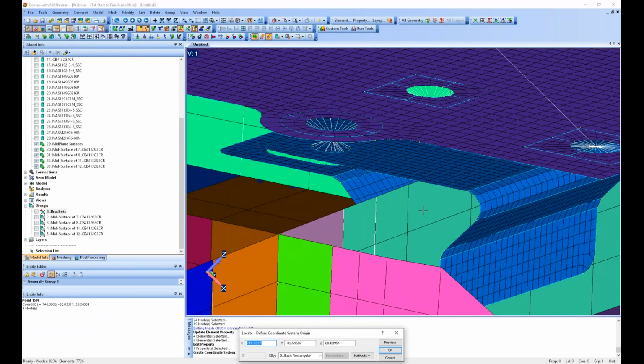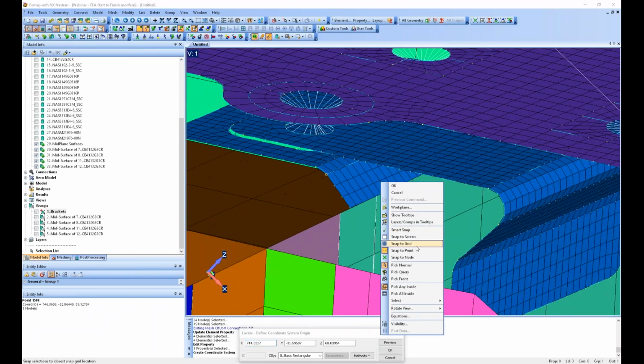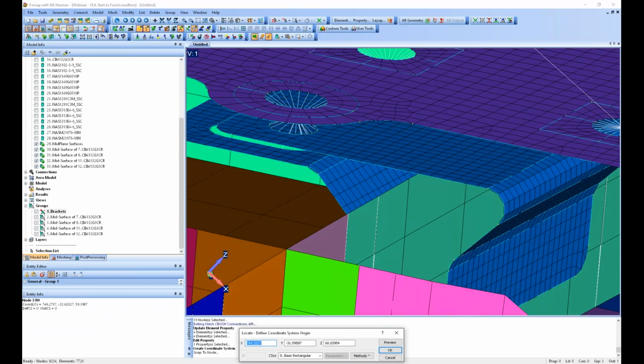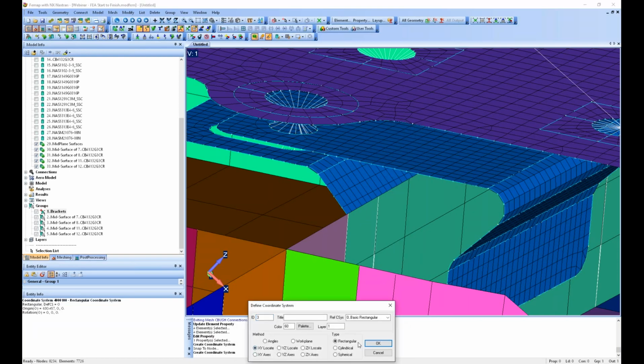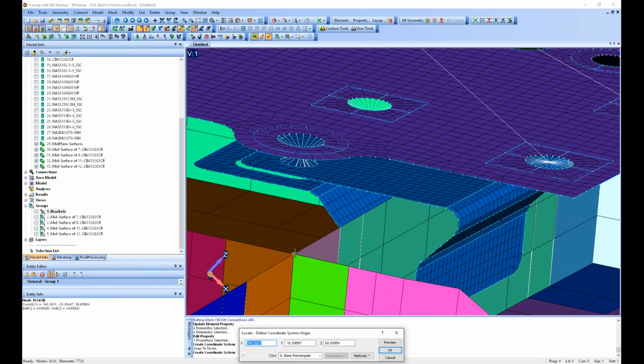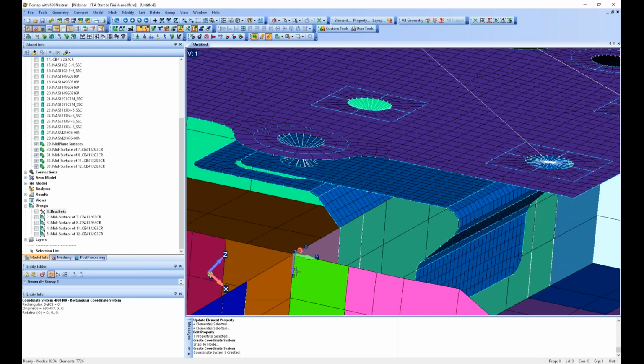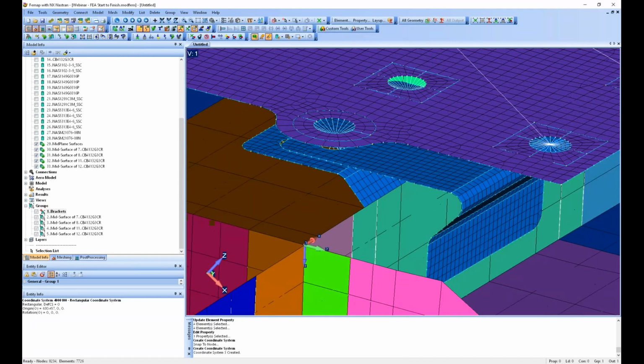And so the first step is it just asks me to select the origin. And so I'm just going to select this node here. And then the x-axis, I can say, runs along the rib. Well, actually, let me repeat that. XY locate. Let me choose a different location. So let me choose this node. And then we'll say that the x-axis runs along the rib, and then in the xy plane. And so that you can see Z is going to be the bolt axis downward.